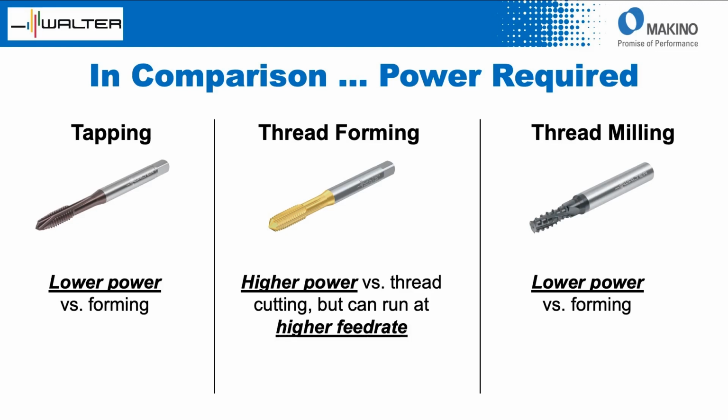As a machining center product manager, what I would say is refer back to the power and the torque charts for that machine, for that spindle, and then look at that RPM that you're going to be running at. Make sure that you fall below those lines.